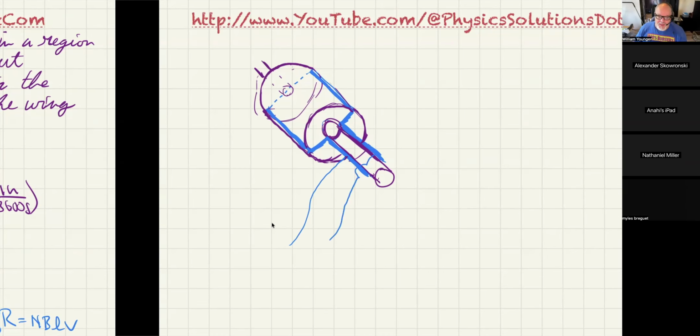And the way it does that is via slip rings. So that's something important. But basically, you can imagine a slip ring as if it's like a bracelet going across here. And because it's like a bracelet, it's constantly touching that wire that's spinning around. And this side also has a similar bracelet, only this bracelet only touches that other wire on the other side. It's got something that's non conductive up against the wire that's closest to me.